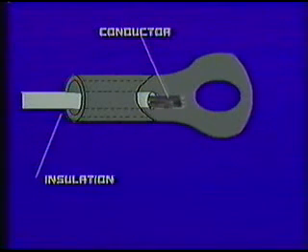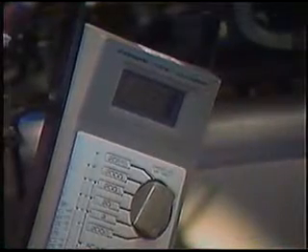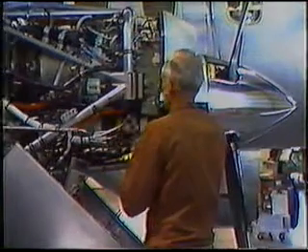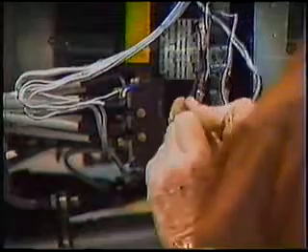What can happen, as is shown here, is that the conductor's insulation is crimped. The worst part is that the crimping then hides the mistake and later makes it hard to detect. Simple oversights like this become nightmares due to their erratic, intermittent nature. Logic, common sense, and knowledge are your best defense for attacking these types of problems. The need for understanding the basic electrical principles cannot be overemphasized. If you're not absolutely clear on what has been covered, re-watch the last 2 tapes again, and by all means ask questions.